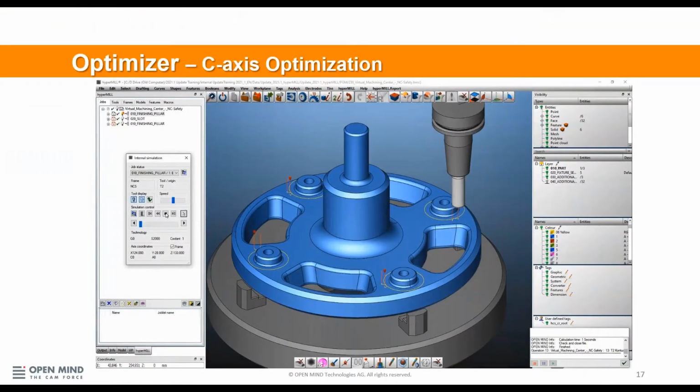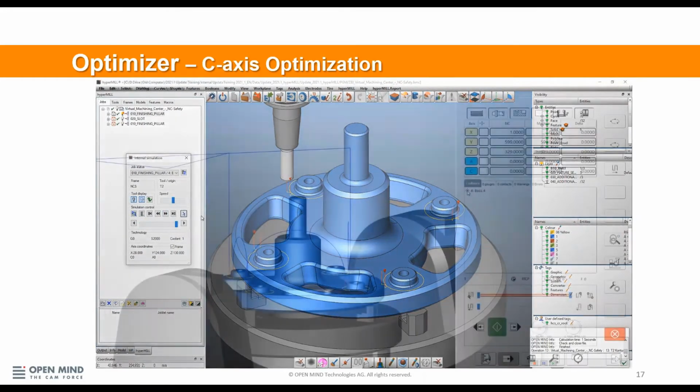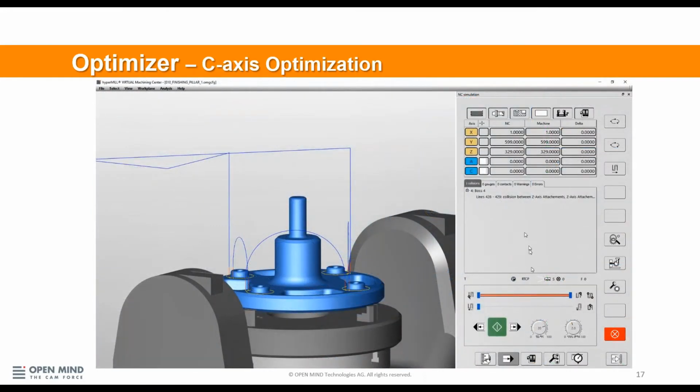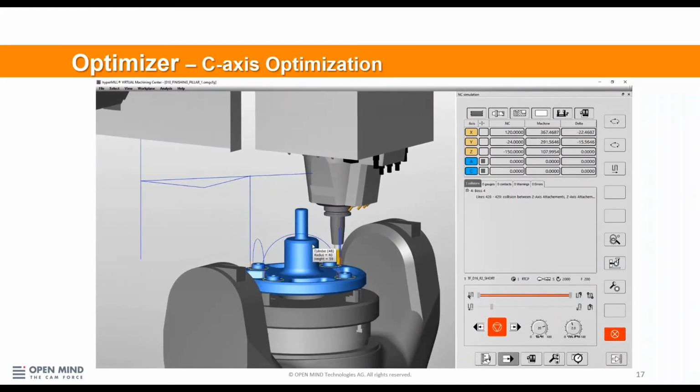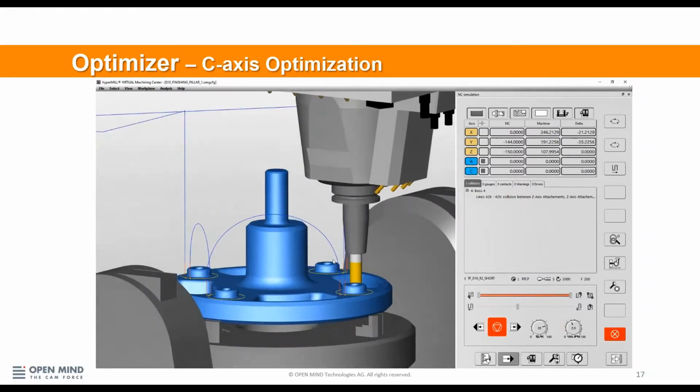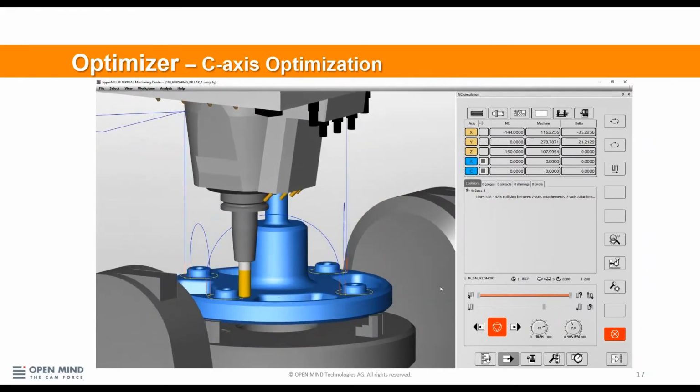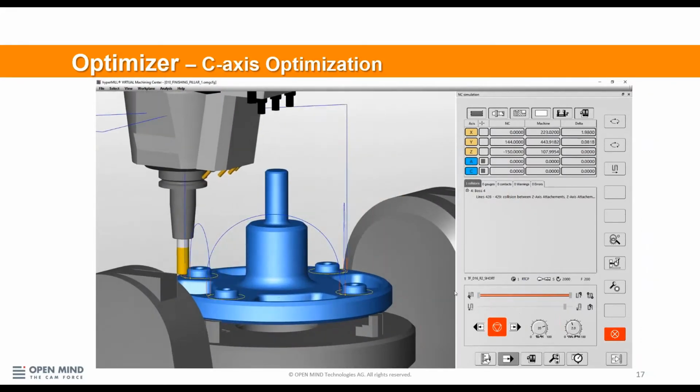So I have here in this example a set of specific machining components that have to be done. They're the 4 bosses in our basic simulation. So you can see the collision checking shows that we have some contact between the top of the part and our coolant manifold. So sticking the tool out is really not an option I'm willing to consider in this case.